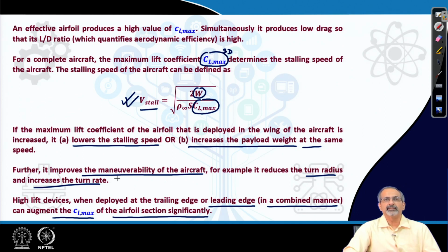So, in this lecture, we discussed further about thin airfoil theory and its application to symmetric and cambered airfoils. Subsequently, we looked at how thickness distribution on an airfoil can influence the stall behavior of an airfoil, and then we came into the high lift devices and we discussed about the trailing edge flap and their effect on the CL alpha curve. Thank you.